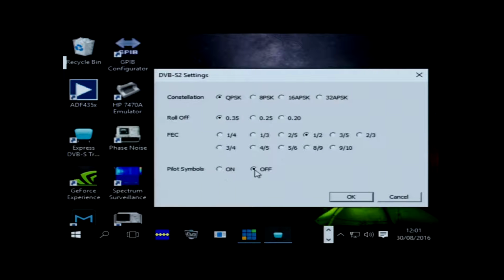If you do not have pilot symbols, it has to do the equalization blindly. In other words, it receives a symbol, it doesn't know what it is, it makes a decision as to what it is, and it feeds that information back into the equalizer to update the coefficients. Therefore, it trains on a blind signal. If pilots are selected, these are known symbols, and the equalizer has 100% certainty of knowing that the information being fed into it is correct.